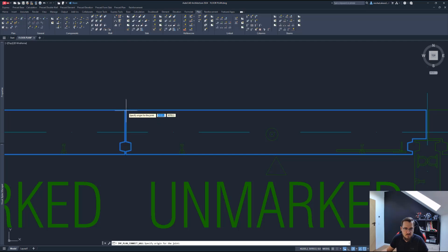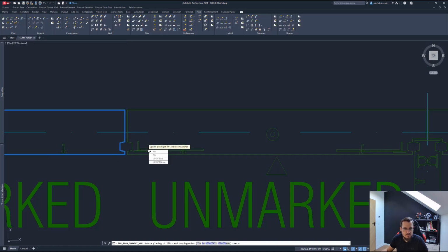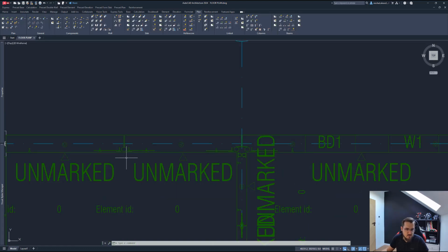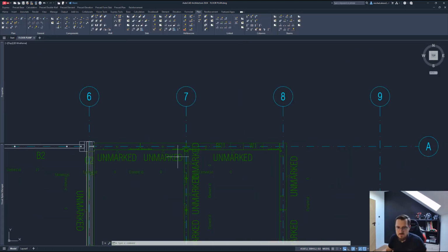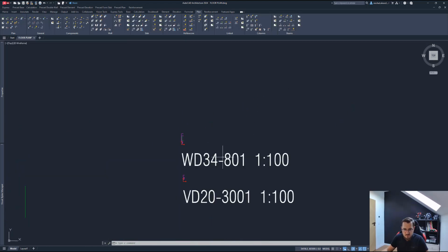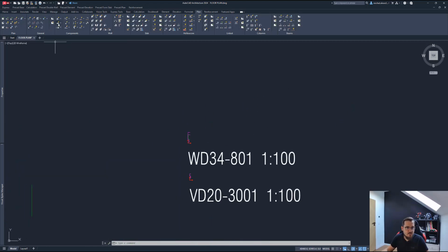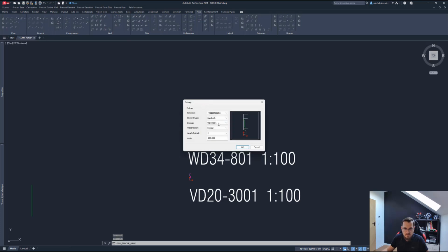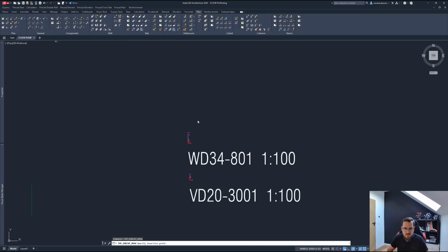Like that, and apply, and yes, up they go. Right. So it works as well for the solid panels. Just FYI. Okay, now let's place that end cap that we had before as well for the sandwich panels. It's this one, slightly different as you can see in the preview. Doesn't really matter. It will be very quick for us, very similar.